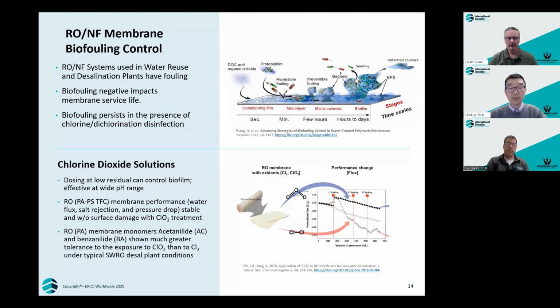Membrane biofouling is actually considered a major threat to RO/NF system operation, therefore often requires regular sanitization to control biofouling. However, sometimes in the presence of transition metal ions such as residual iron and manganese, the peroxide or PAA-based sanitization reagents will be detrimental to RO and nanofiltration membrane systems.